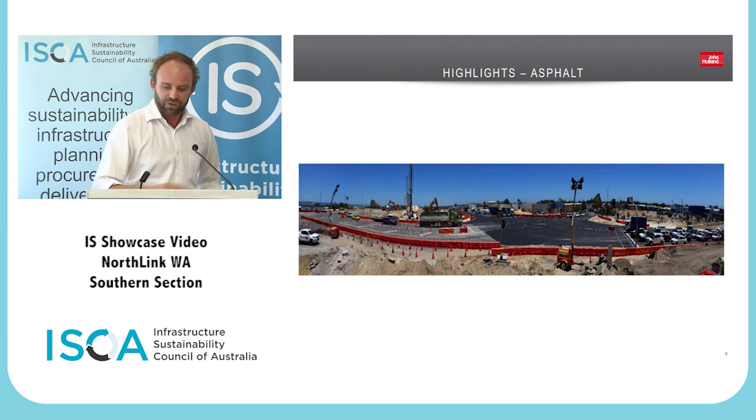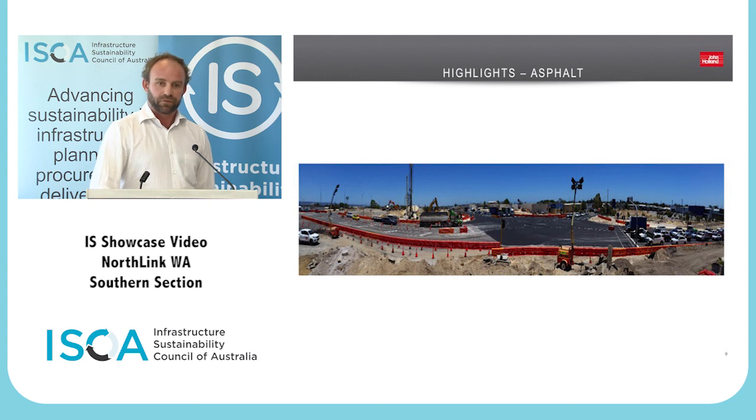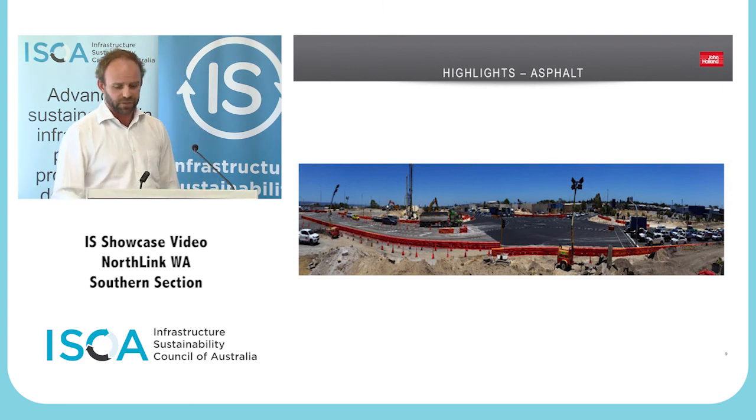Okay, so I mentioned asphalt there. Asphalt is important on this road. This is going to be a road used heavily by the freight industry. The road needs to be durable and to be able to withstand road trains and the like. The asphalt is therefore quite thick. It's what's referred to as a full depth asphalt. Approximately a foot of solid asphalt is incorporated in the road surface. Obviously that has big impacts.